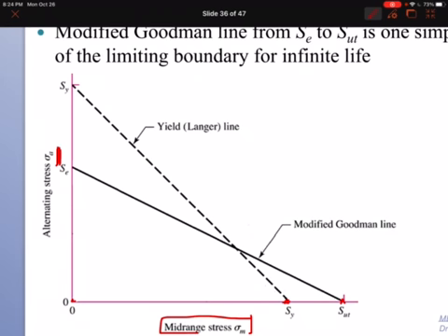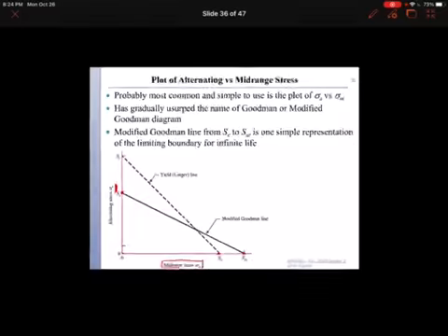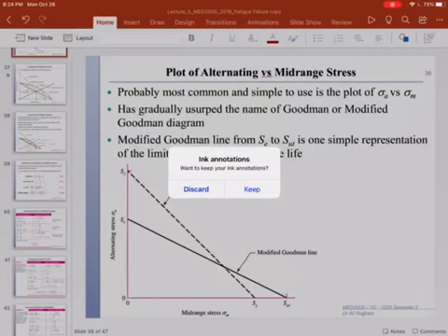Once alternating component is increased, then we will have fatigue or dynamic condition. So in this case, the alternating component is at maximum value when mid-range is 0, that means we have completely reversed. And for completely reversed, the limit is endurance limit. Okay, so starting from these points, we have few methods that can be applied.